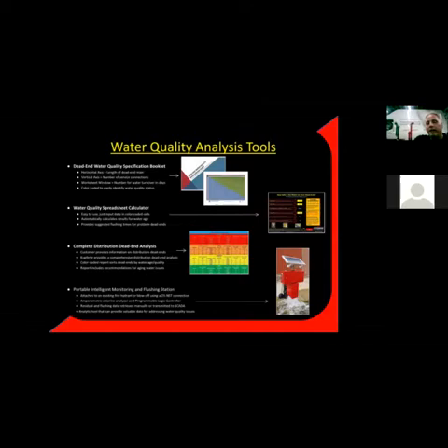And then on the other axis of this particular chart at the top is the number of service connections, up to 35. So if I know I have 12 houses on the line and the line is so long, I can go over and find the corresponding cell, and it gives me a number, 4, 2, 6, 8, 10, whatever it might be. And that's the average amount of days it takes that number of service connections to turn that particular line. Most houses on average in the US use about 350 gallons of water a day.